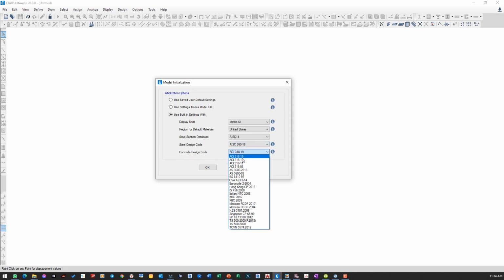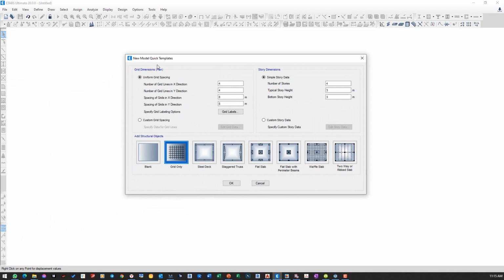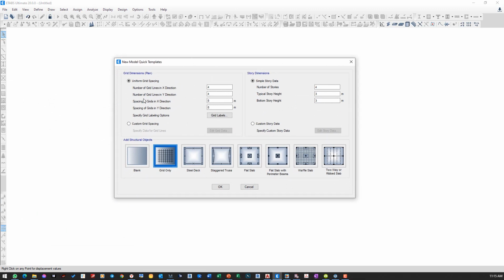I will select ACI 318-14. Sorry, 318-19, with the M. Click OK, and you get the new model quick template.